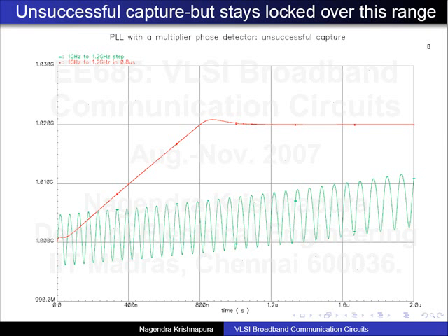Okay? See, the control voltage is what causes the VCO output to increase. Now if the control voltage tends to go positive, the output increases and the difference reduces. Now, before being applied to the VCO, it is getting attenuated by the loop filter. So there will be a control voltage increase, but not as much. So that's why it is not able to capture fast. Okay?